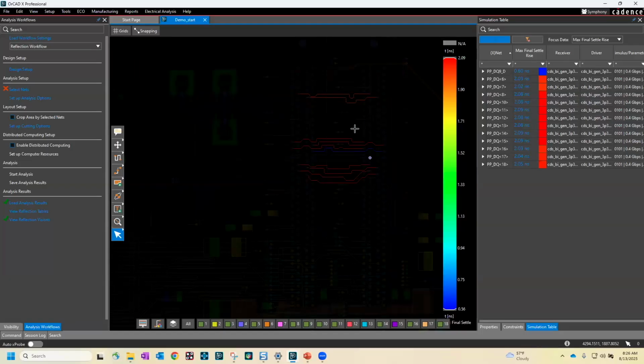So this is kind of like a first order analysis to an ultimate sign-off analysis, right? If you had a DDR memory interface, you're going to eventually run a full system analysis, analyzing every bit of the bus at the time, getting it down to eye diagrams and some sort of verification utility. But if you do this first and flush out all these problems, the chances of that final analysis being successful are much higher. And if you were to run that final analysis and you failed there, this would be the way that you would debug that failure.